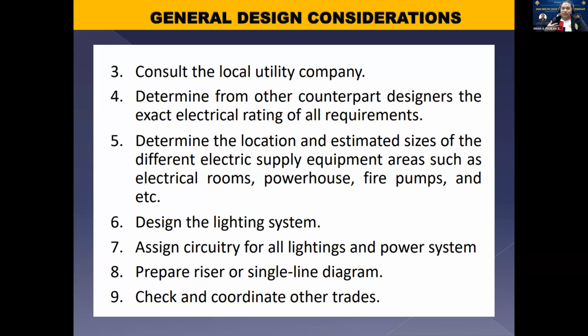But as for me, based on my experience, I use the higher value, because we know we are safe and we still have allowance, just in case they have additional loads. So like I said, the actual ratings of the equipment given by the other designers can be used when assigning to specific outlets or specific circuits, as the actual rating in the branch circuit. But for the feeders, I would recommend using the higher value from what we computed in low density.